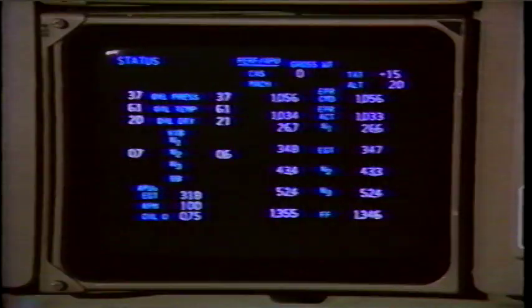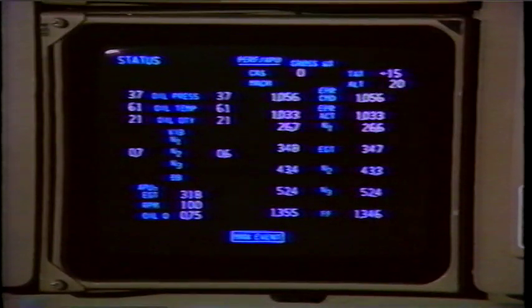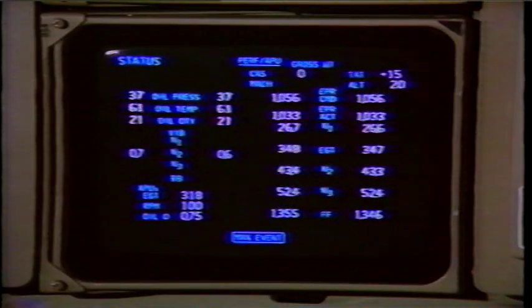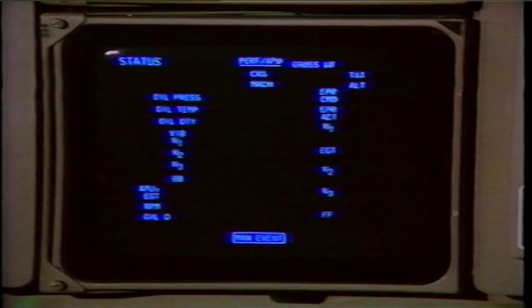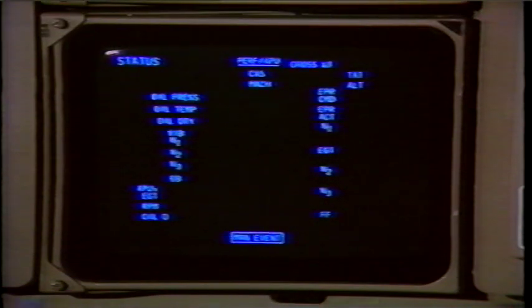When a system page has been selected, pressing the manual event read switch will cause the manual event queue and box to appear at the bottom of the display. If a manual event had been recorded, the data field will display the recorded values. If no manual event had been recorded, the manual event queue and box will still appear, but the data field adjacent to the system parameters will be blank.